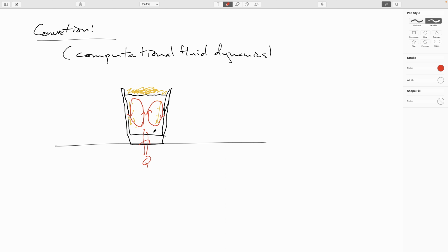So the bubbles actually get dragged down the middle, brought up the top, and they finally emerge to the surface in the middle of the beer, which is why you get that crown on the top of the head of Guinness. And it's not an optical illusion. The bubbles really are going down, but they're trying to go up, but the fluid is going down faster than the bubbles are going up in the fluid along the edges of the glass. In the middle of the glass, they are going up.